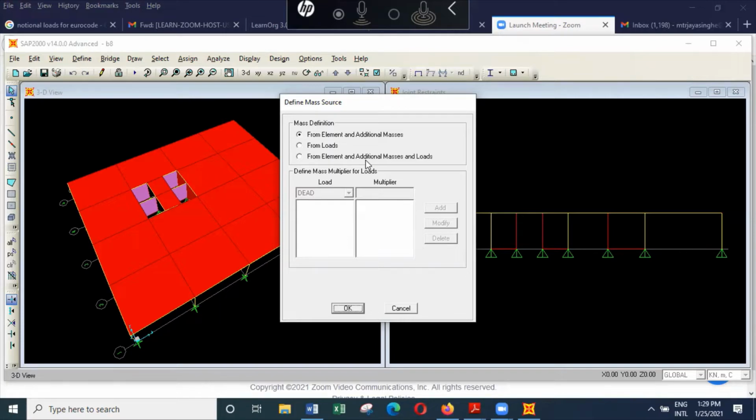from the additional masses you are adding. So that means, instead of the handrail, now we will add the mass, because in the actual model we are not modeling the handrail. But still, you can represent the mass of the handrail by allocating a certain mass to a joint.